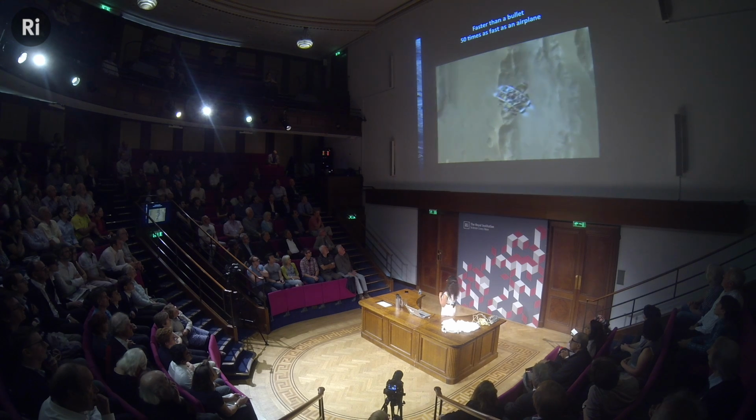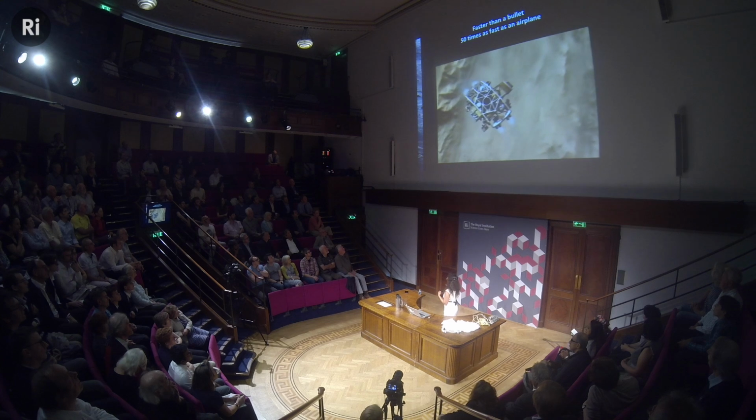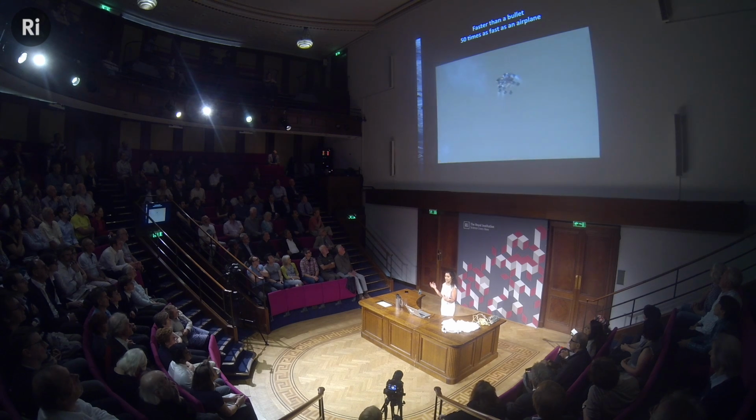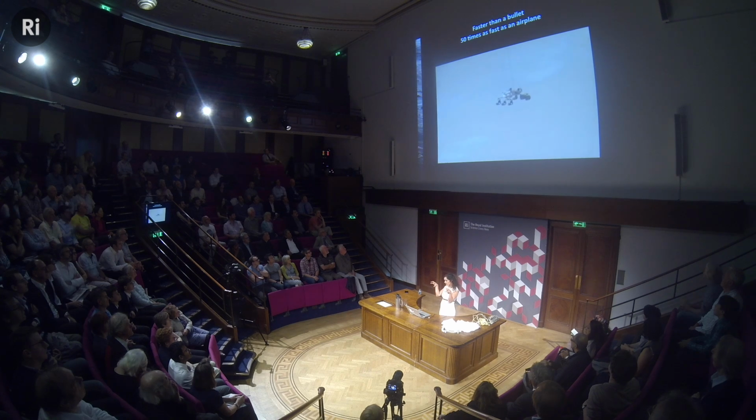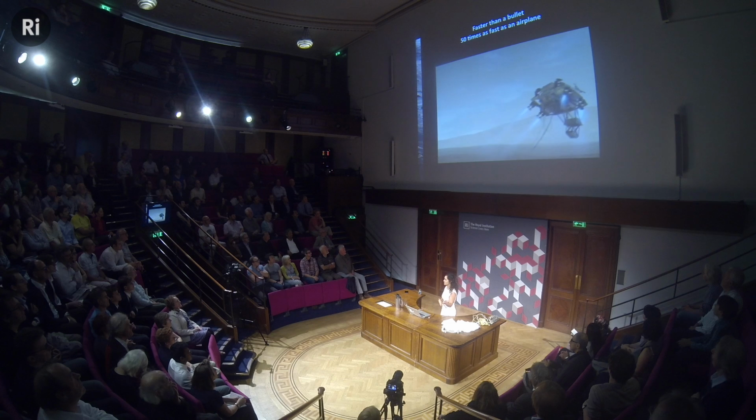And we had a total of 8 retro rockets actually going towards the ground. When we were around 60 feet above the surface, we started to lower the rover on a tether. This is called the sky crane maneuver. And we can talk about it, might be good for a question and answer session, if you want to know why we chose to do certain things that we did. But we primarily do it to increase the distance between those retro rockets and the surface of Mars, because they end up kicking up a lot of dust and sand, and you'll see that in a moment. It also allows the rover to be the landed platform. So instead of carrying an airbag, which you have to carry all the way down to the surface, you just touch down on your wheels and you're ready to go.